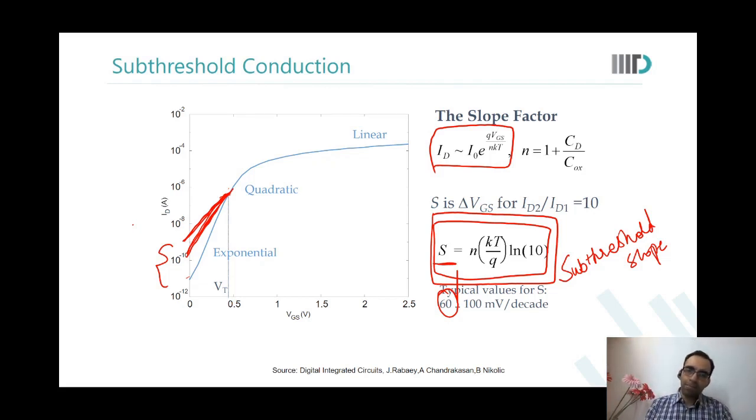So these different red curves are basically different technology nodes, right? Yes, having the same VT. We won't call them technology nodes. It could be 65 nanometer technology only, but one could be from TSMC, another from Global Foundries, another from Samsung. So though they have the same VT, the subthreshold characterization is different. So whenever you look at a technology, you cannot just look at what the VT is.